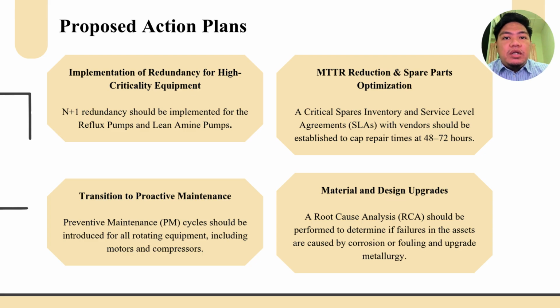A root cause analysis, RCA, should be performed to determine if failures in the sweet gas cooler and trim cooler are caused by corrosion or fouling. Metallurgy should be upgraded based on the RCA findings. The justification for this is that the frequency of failure events is reduced by improving the inherent reliability of these static assets, which is critical given their high failure criticality index.